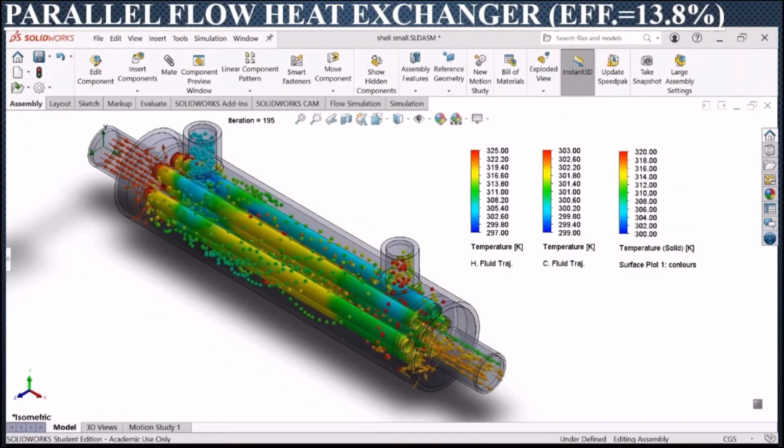This slide shows the animation of a parallel flow heat exchanger. In this type of heat exchanger, both cold and hot fluids are flowing in a parallel direction. It's clearly shown that the hot fluid enters the heat exchanger from the left header and leaves colder from the right header, while the cold fluid enters the exchanger from the top left side and leaves hotter from the top right side. The efficiency of this parallel flow is 13.8%, which is less than the counterflow one.